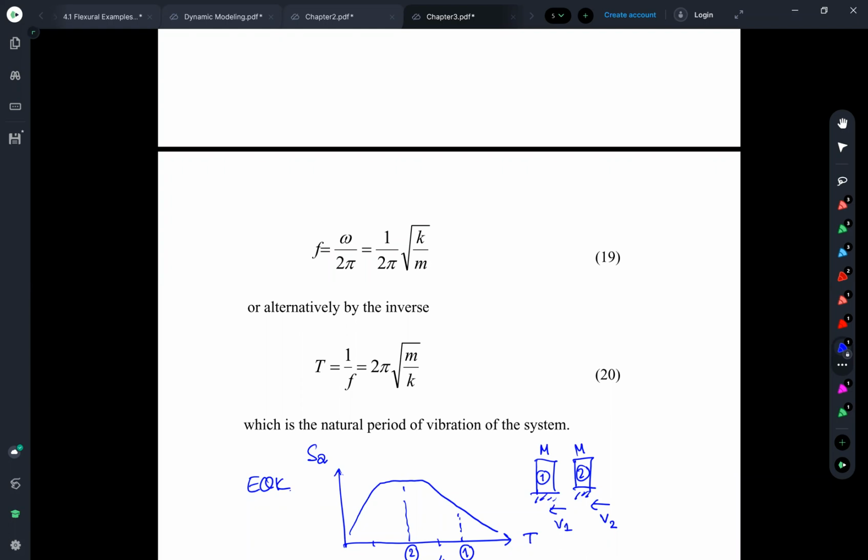I do believe it is really easy to remember. I always remember something like this: omega equal to square root of K over M, right? And from the omega, you can change into the circular frequency by saying that omega is equal to 2 pi f. And this 2 pi f, in fact, is equal to 2 pi over the period T, right? So every quantity about the frequency or the period is related with the stiffness and the mass.